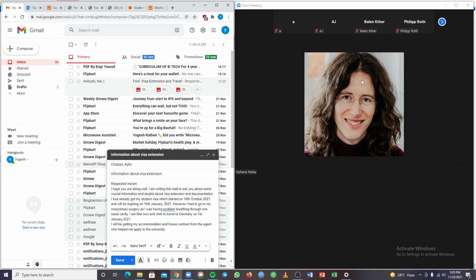Our seat A, the position we want to describe, is our point mass that we can describe in two systems. The leading motion is the rotation of the big platform itself, with omega 1, alpha 1, and our relative motion is the rotation of the smaller platform with omega 2 and alpha 2.